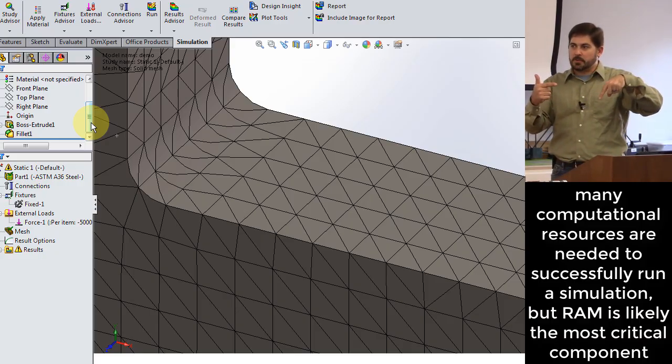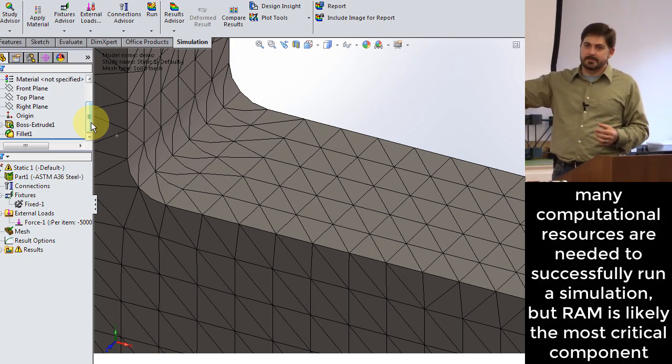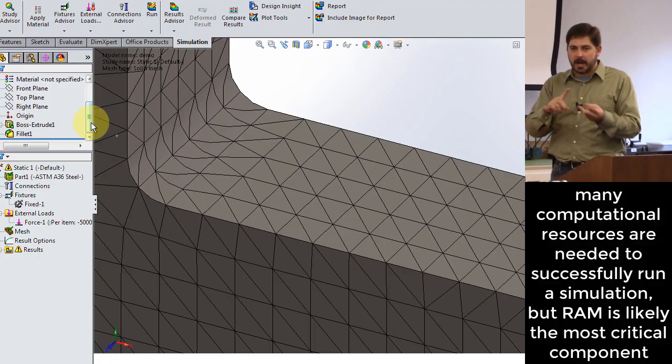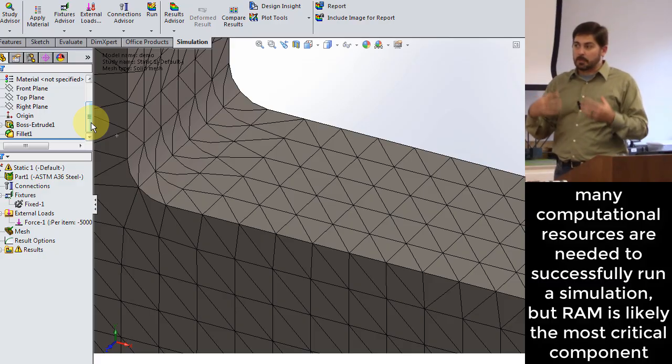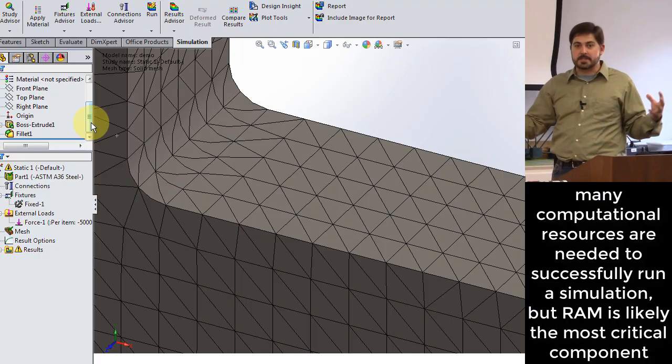So there are all these relationships set up per element: how much does it deform, whether or not it's in equilibrium, how does it interact with all the pieces around it? And the result is a really large system of equations. Look at the number of elements, and there's multiple equations per element, and it has to solve that giant system of equations in order to figure out all those forces.